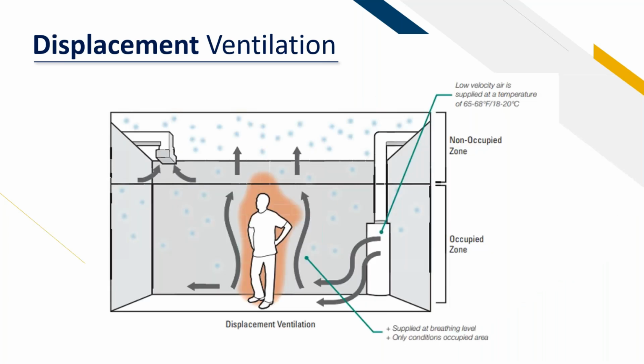Like I said, it is a single pass system, which really benefits in helping keeping the occupants healthy and really improving indoor air quality. Because of that single pass system, for instance, if somebody sneezes or coughs in that space, with displacement, it is typically going to be lifted out of the zone very quickly without impacting anyone else. As a single pass system, there's no mixing of the air. With a mixed air system, it could take up to an hour or two to really get any sneezing, effluence, and stuff like that out of the space. So it's very much improved indoor air quality.